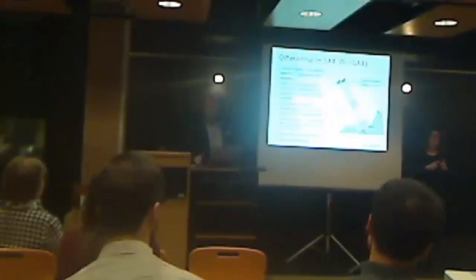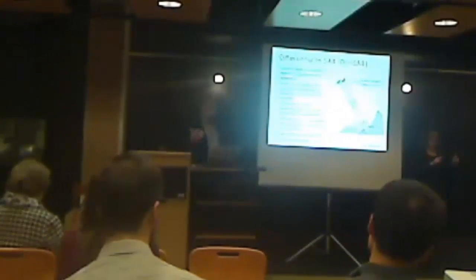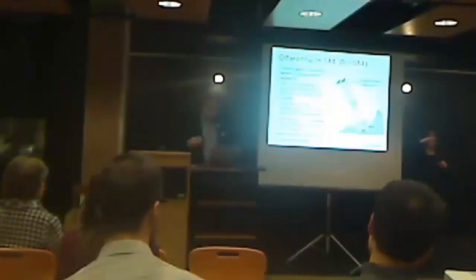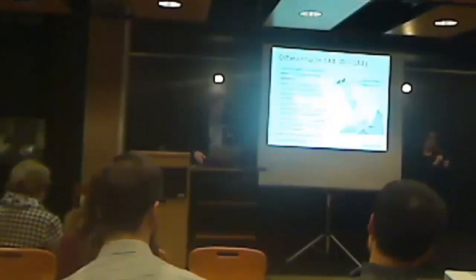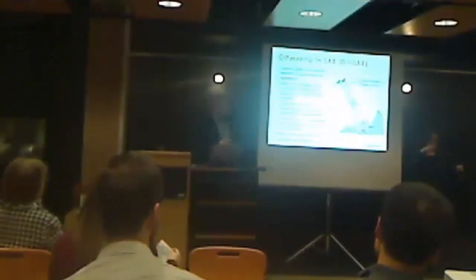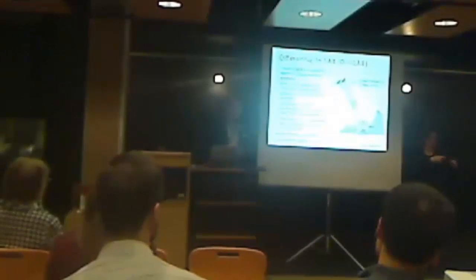Then we do a change detection of 2 interferograms, and we can do what's called a differential InSAR. The path of the satellite remains constant, the speed of the wave remains constant, so the only thing that changes is the distance between the satellite and the ground, and that's how we can get ground displacement values. Again, this can be done daily, weekly, monthly, or even on a yearly time scale.